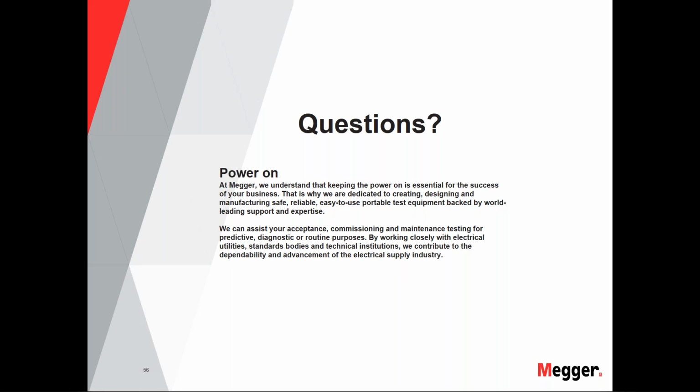Thank you. Next question is for Danabal. On what loading points should measured third harmonic for stator ground relay set points? Yeah, third harmonic measurement in general, even including IEEE standards, we measure at 100%, which is basically 1 per unit of the generator capacity. So for example, in a 100 megawatt generator, it may be close to 5 to 6 volts of third harmonic generation that happens. All right, thank you.